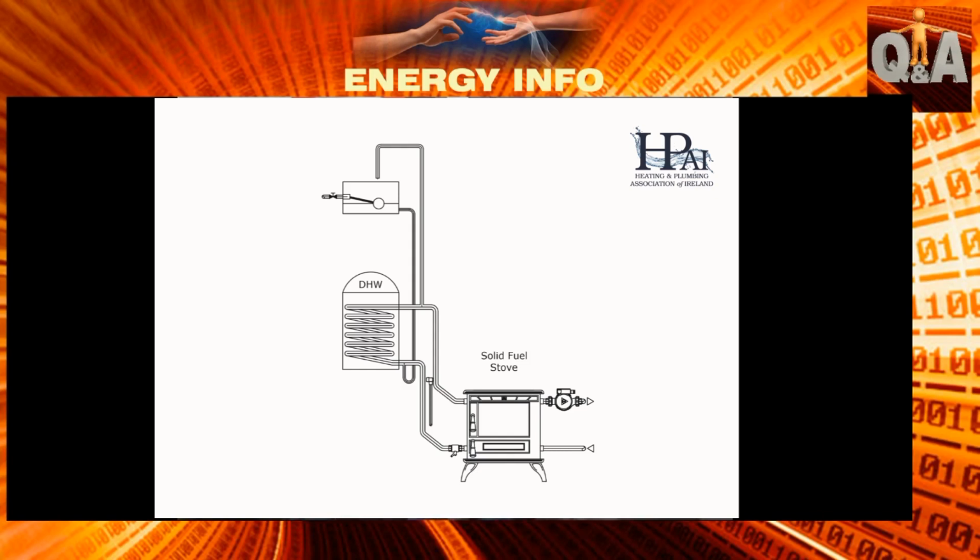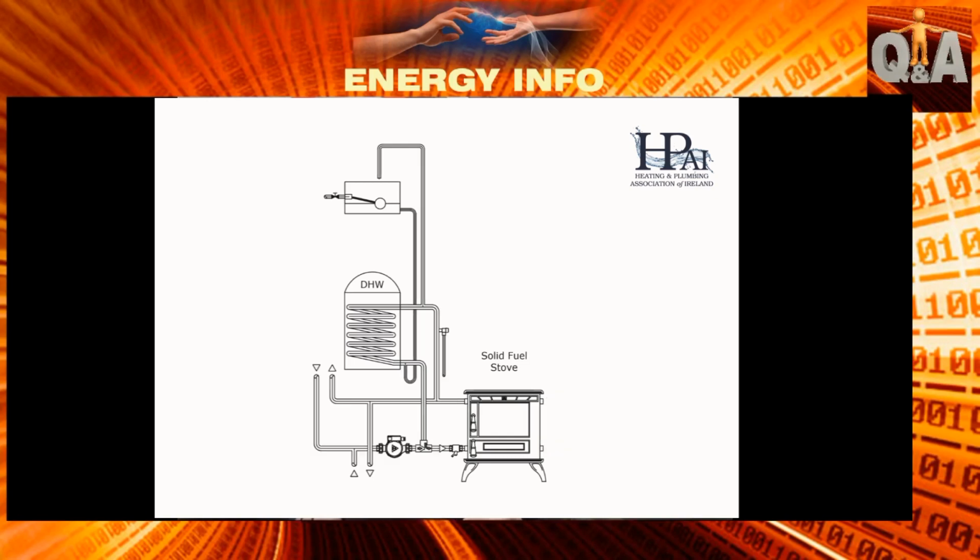The same thing applies if you have a 2-pipe system. Some people think it's even better because you have a definite amount of water that's doing a very definite job. Where the water leaves the stove and heads out, it meets a T. It can rise up by natural occurrence, by thermosiphon, is cooled by the water in the cylinder, and falls back down.